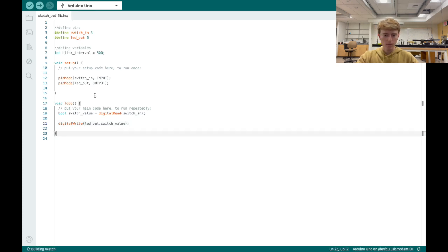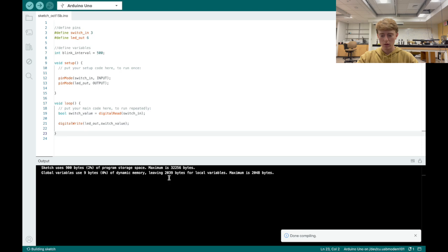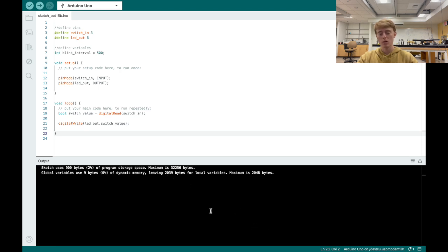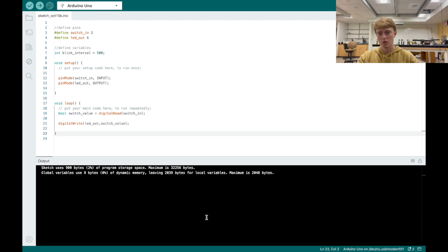All right, so now let's run this code. So first things first, I'm gonna hit compile to check and make sure that I don't have any errors. Okay, so there we go, we're done compiling, no errors, so we're good to go. So now let's upload. All right, so we're uploading. And remember, compiling is actually sort of an optional step. You can just skip that and go straight to upload, but it's kind of nice to see whether you have any errors before you try to send it to the Arduino board itself, okay?